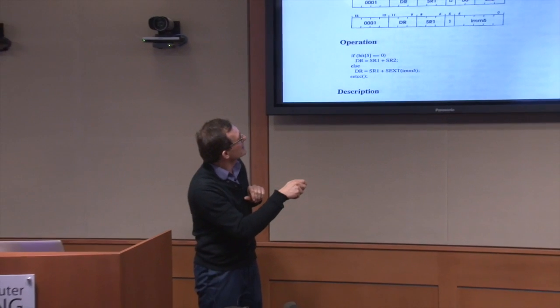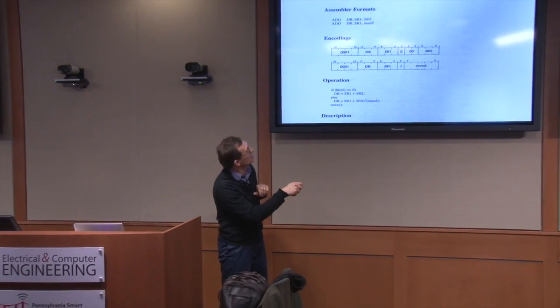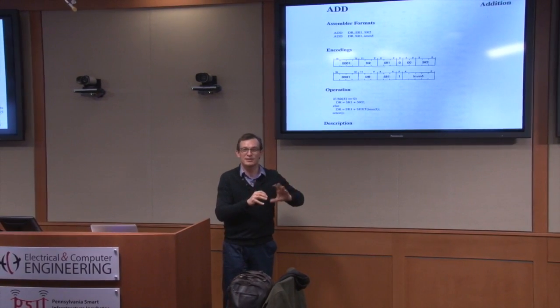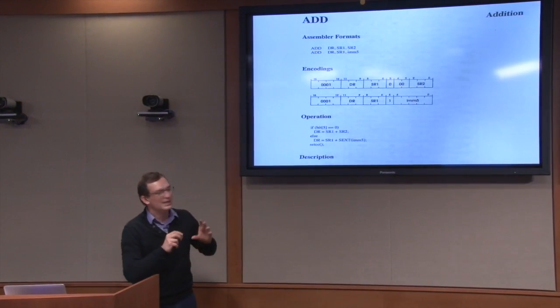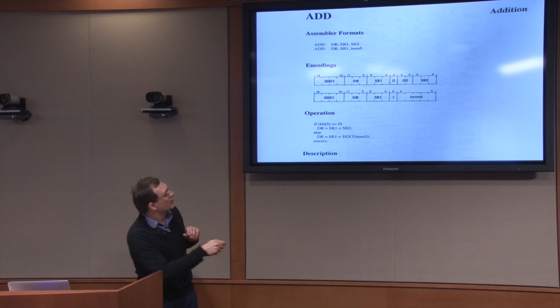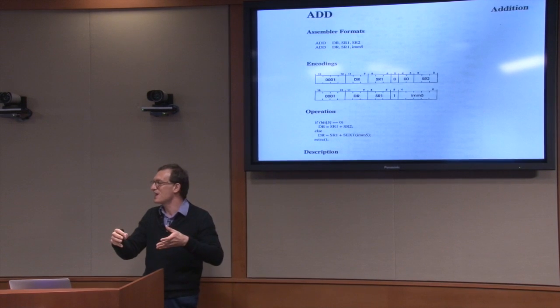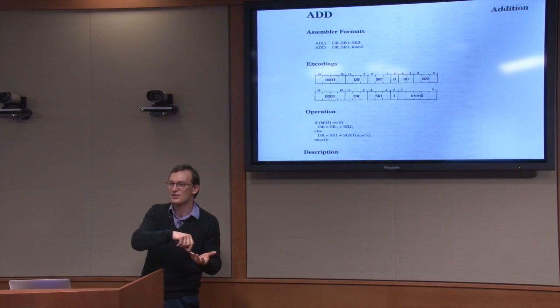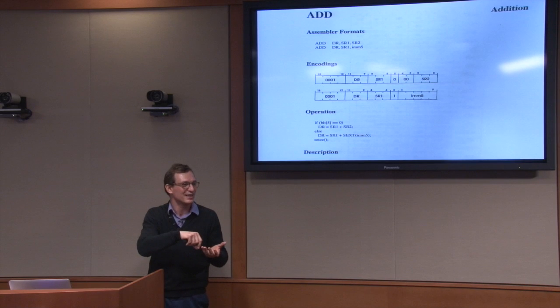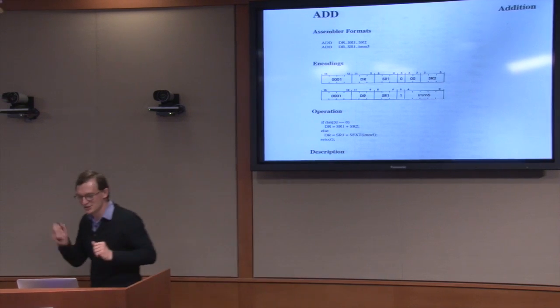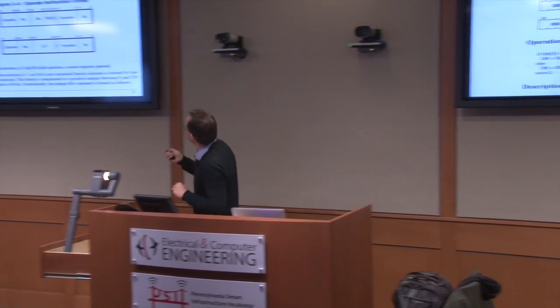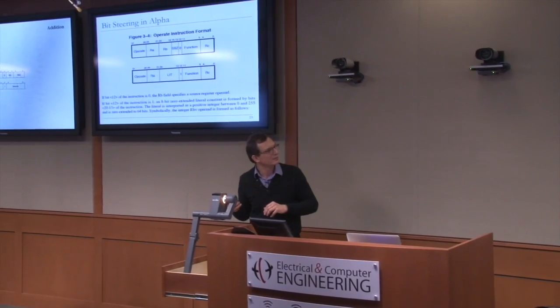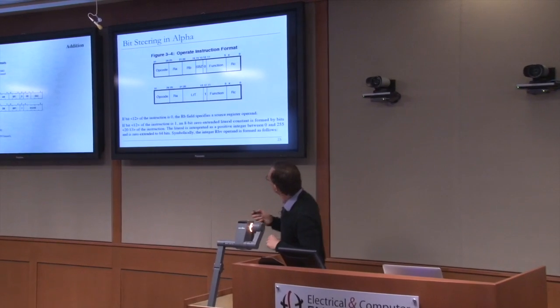The steering bit gives you a lot more power in the instruction. Now you can have different operands, in a sense. But it also makes the decoding a little bit more complex, because now the interpretation of what's coming next depends on the interpretation of a previous bit in the instruction. So we'll get to that, actually. Okay, the other examples over here, I guess they're symmetric.